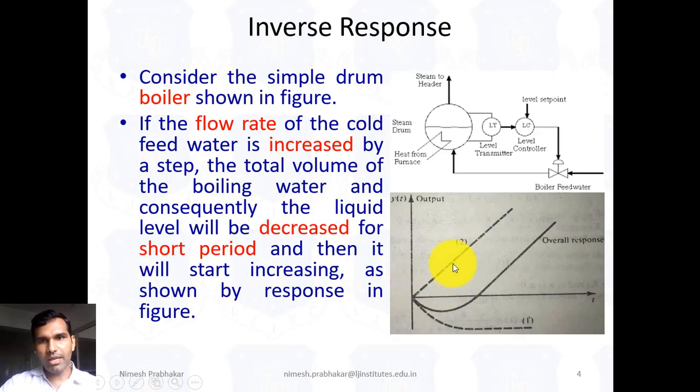But when we give cold water as input, initially the water level inside this drum is reduced. This graph indicates the decreased level of the water inside this tank. The liquid level decreases for a short period of time, and then when the inverse response effect is gone, it goes up to here. So this is the overall response.